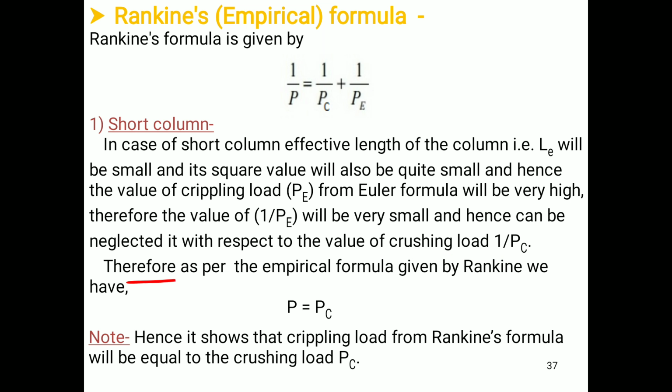Therefore as per the empirical formula given by Rankine, we have P equals Pc. It shows that the crippling load from the Rankine formula will be equal to the crushing load Pc. P will be equal to Pc. This is for the short column only.